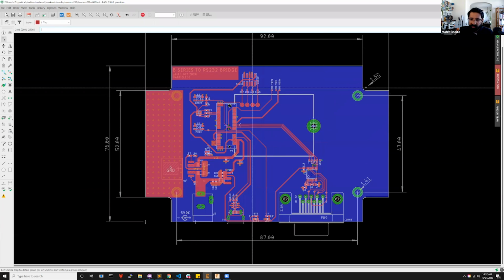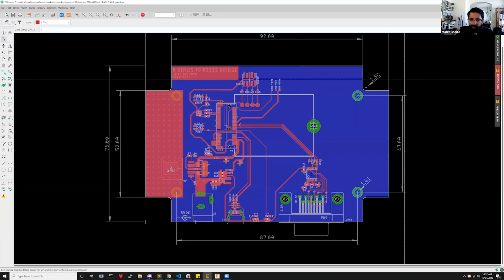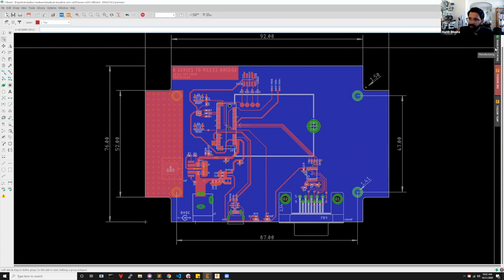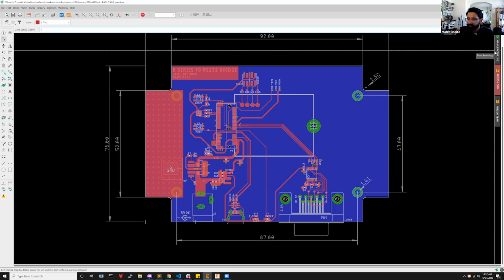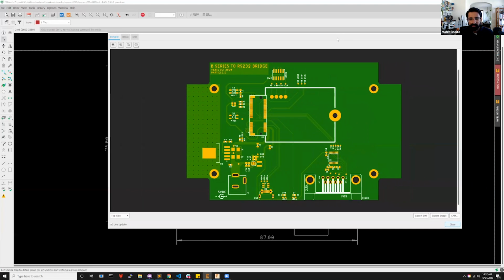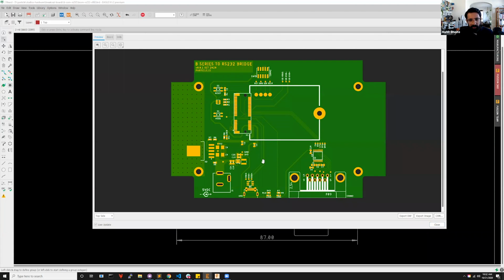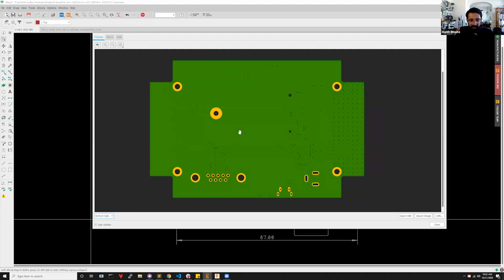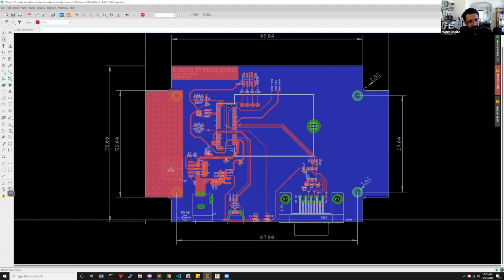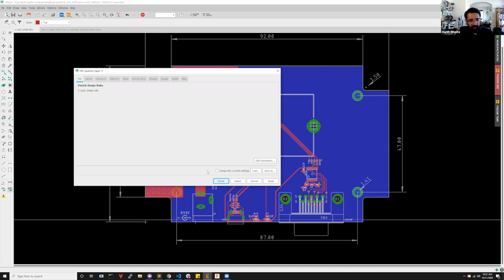Eagle also allows you to quickly verify your design, to see what it would look like in its physical manifestation by clicking on manufacturing. And over here, you can see if you have made any mistakes, like putting the silkscreen over something, or missing a particular via. It gives you a good glimpse into what the physical board will look like before you press generate Gerbers and whatnot. You can see top and bottom, they look clean, so that's good. We'll also do a quick DRC run on it to see if anything comes up. Hopefully, let's keep our fingers crossed.